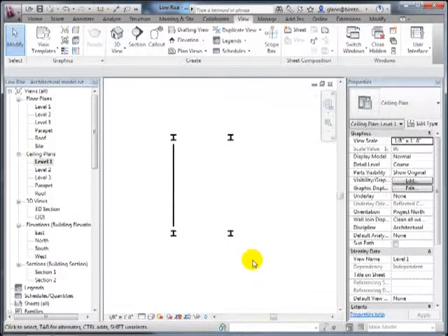Okay, there it'll be. Now, notice it's showing up here as a single line. Often structural engineers like to look at their diagrams as single line views as opposed to showing the full 3D dimensions of things, so it keeps things a little bit simpler. You can keep it that way. If you want to see a little more detail, we can turn it up from a very coarse level view to more of a medium level view, which will then actually show the 3D bounds of what's going on.